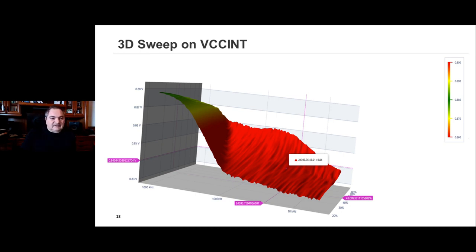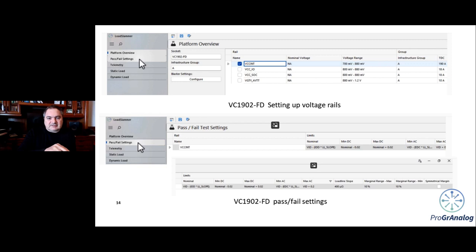I'm going to move to slide 15. This is really kind of where the test engineer leaves. With Xilinx, you would have your PDM, the Power Design Manager tool, and that would tell you, like it did in a previous slide, how much current you can expect to be pulling from the device, given the amount of utilization and clock frequencies, etc., that you're going to target the fabric with.